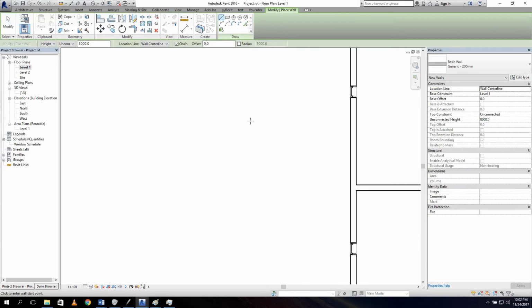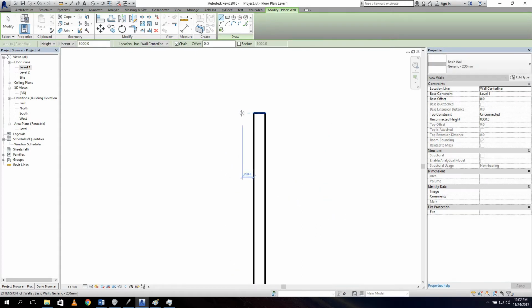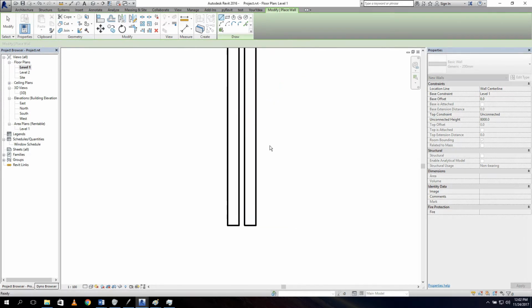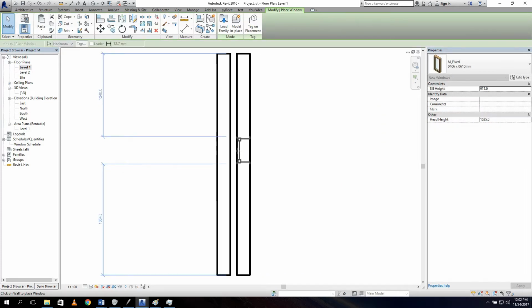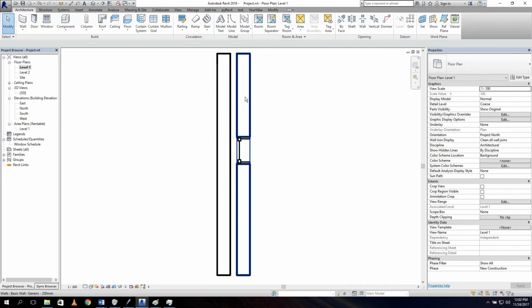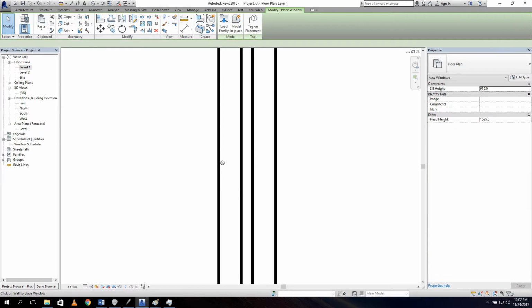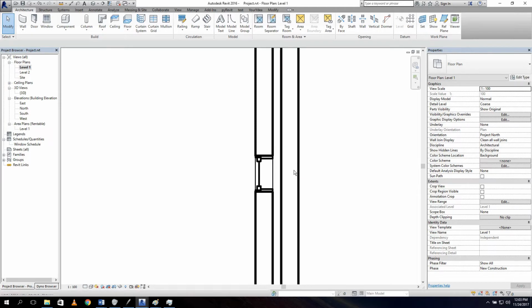Select wall. If I draw a wall here, and I draw another wall here, like so. And if I say, alright, I want to have a window inside my wall, a window, like so. This is our inner wall, this is our outer wall, this is brick, this is lime. And it won't make an opening in the outside wall if I drew my window in the inside wall. And if I delete it and I create a window in the outside wall, it won't make a hole in the inside wall.